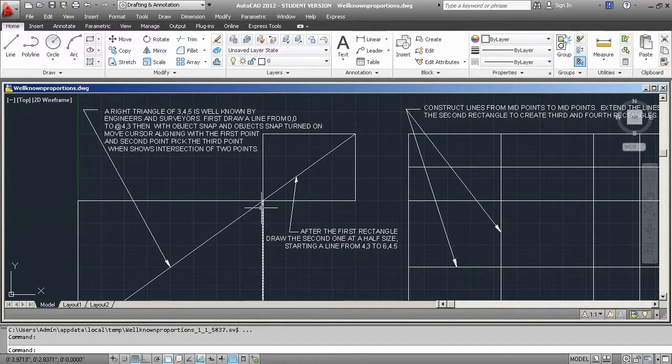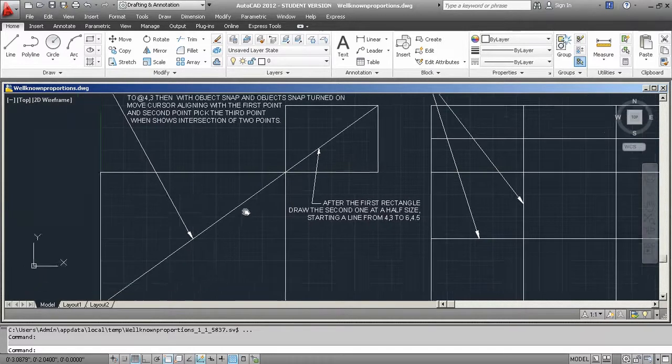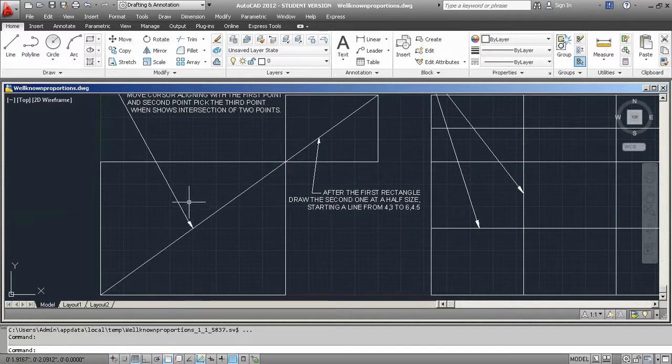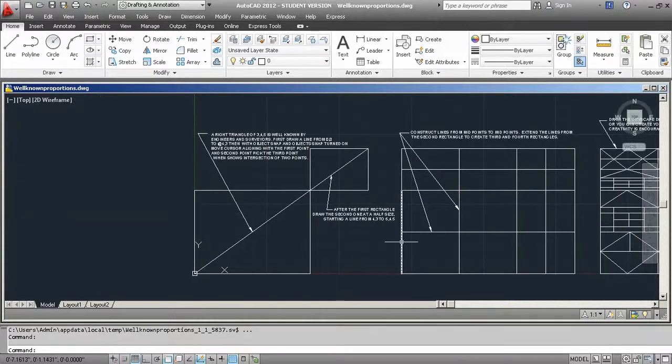Proportions are important if there's going to be a change of design. If you're creating 2 rectangles, either they're supposed to be the same or somehow proportionally different from each other. You're going to be generating the first rectangle from individual lines, and the second rectangle perhaps from the rectangle command. In the meantime, you're going to be using relative coordinates and polar coordinates.